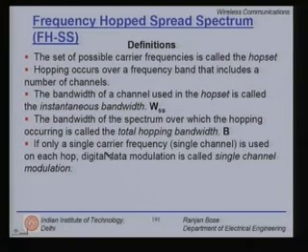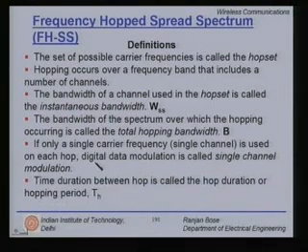If only a single carrier frequency, that is a single channel, is used on each hop, the digital data modulation is called single channel modulation. The time duration between hops is called the hop duration or hopping period, Th. So these are some of the definitions related to FHSS.